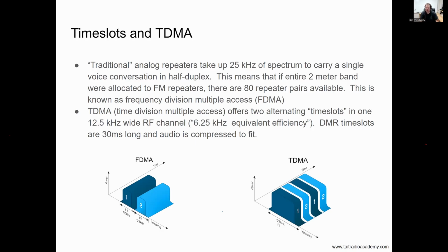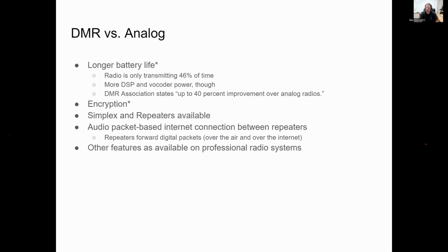So I think there are a handful of manufacturers that make radios with transmit receive switch, generally pin diode switched, because you'd wear out mechanical relays pretty quickly with your DMR transmissions. And from a repeater side, however, it doesn't matter, because again, that's full duty cycle. So Crescend makes a popular amplifier, and Motorola has 100-watt repeaters and things like that.